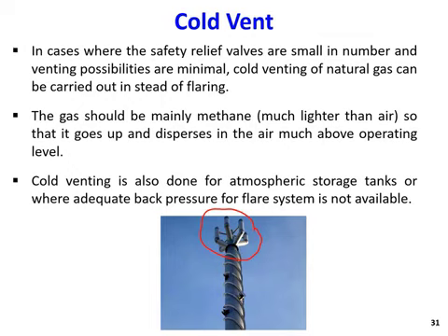It is when the amount of relief gas is small. We don't have a big amount of relief gas or vent gas, so we don't really need to create a flame for a small amount of gas or natural gas. We can just vent it the cold way without burning.